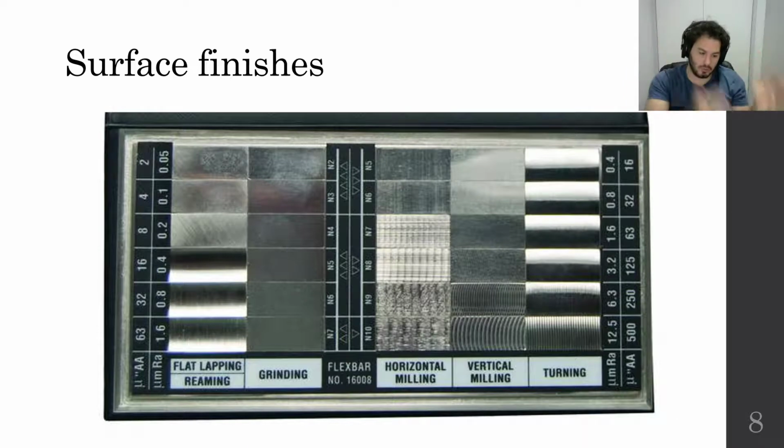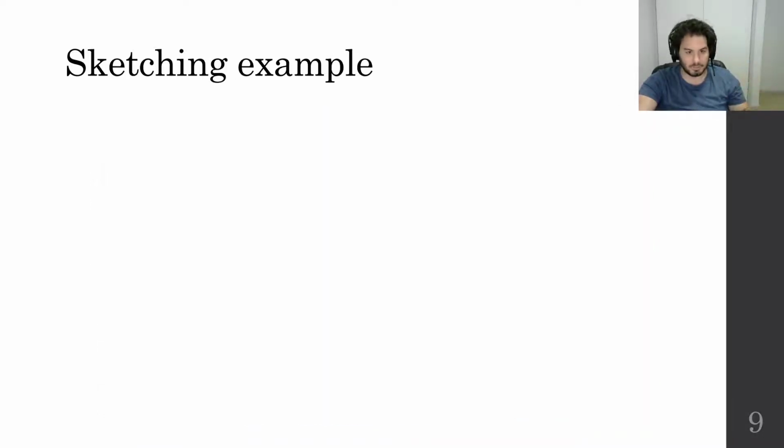But every time you do that, you cost time, which means you cost money, you cost resources. So what's the worst acceptable surface finish is generally, again, the one you want to go with because that saves you resources to spend where they're more important. These are just two traps for young engineers that fall into them all the time, speccing stupidly high tolerances and stupidly high surface finishes. Cool. All right. So that's a bunch of the background information that we wanted to think about.